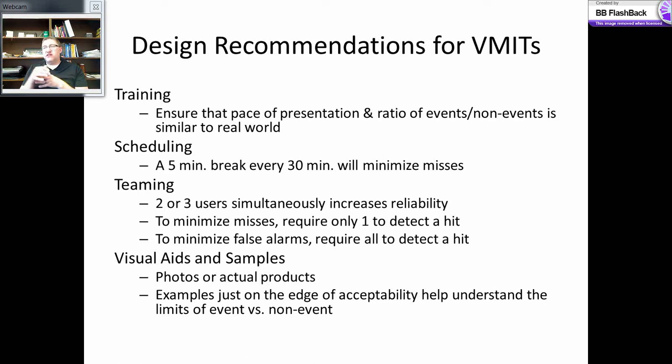There are good reasons that a signal might be missed. Like I said, for airbags, perhaps it's a smaller dent on just one side of the vehicle and the other side sensors might miss it, but still you have 5 sensors on this side, and if only 2 of them are reading it and 3 of them are missing it, maybe there is something there, but it's not very significant, or maybe it's that 1 in a million chance where those 2 sensors are actually failing at the same time. So by having a 3 sensor or more rule, you've minimized false alarms a lot, and you've pretty much minimized misses, although probably you'll get a few more misses than false alarms. But anyway, there you go.